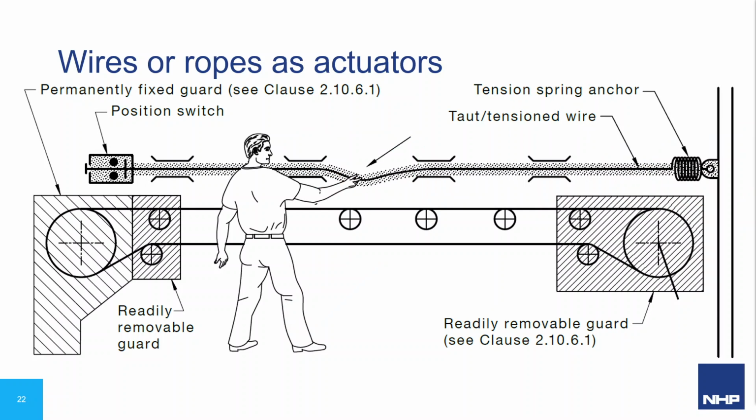In this case, what is required is a tension spring on the other end of the rope, which gives the operator something to pull against and create slack in the rope. Alternatively, a second emergency pull wire switch can be fixed on the other end of the rope, as its own internal tension spring can provide the same effect for the other.